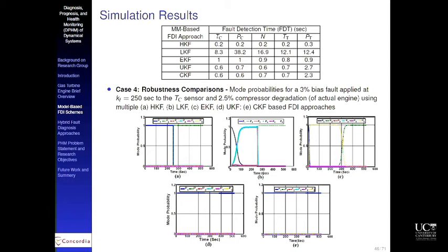Our Kalman filter approach takes care of the linear filtering and the onboard engine model, versus the linear Kalman filter, which does not take into account that onboard engine model. Then the extended Kalman filter, which is one level higher complexity of the filter, where some nonlinearity information is incorporated. Then the extended, unscented, and cubature Kalman filters. These are much more complicated nonlinear filtering.